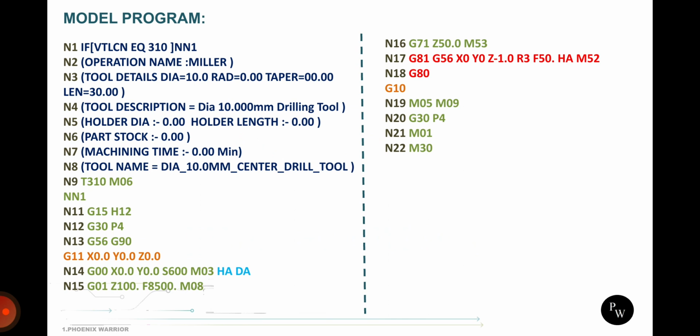So the next line is a positioning line. What speed parameter do we want to give? So the speed parameter depends upon the material hardness and the geometrical parameters of the tool. It depends upon these two categories. So in case you are using a very hard material, and you directly put in a 100 drill, it will affect the cutting. So you should consider the tool geometry as well as the work hardness and work material. So this is the main thing.